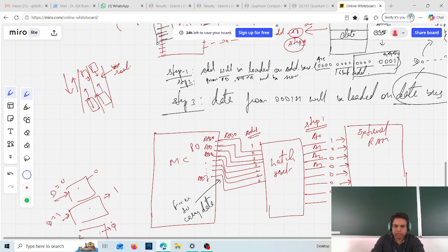However, to enable this latch, to store the input, there is a pin from the 8051 microcontroller called ALE. This will send a high pulse signal, that is binary one, to this latch to enable the latch. Unless this latch is enabled, the output will not be the same as input, meaning this latch is not going to store the input value. So this ALE pin inside the microcontroller is used to enable this latch.